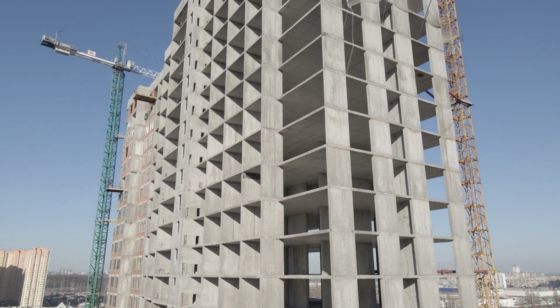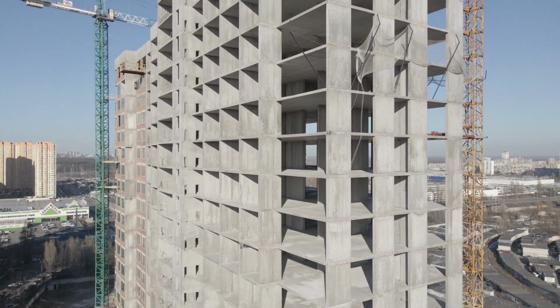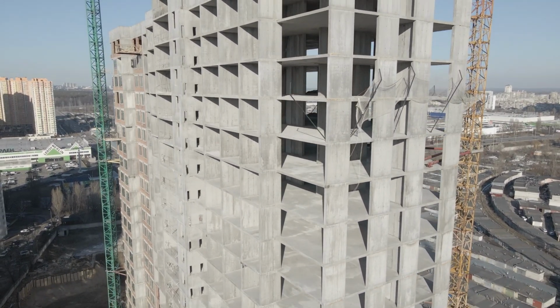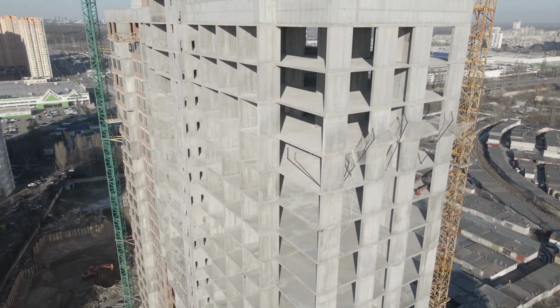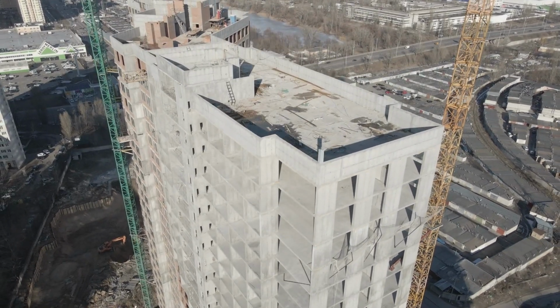Timber is the most common material used for formwork. The disadvantage of timber formwork is that it will warp, swell, and shrink. The application of a water impermeable coat to the surface of wood mitigates these defects.